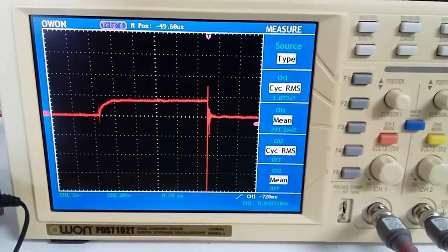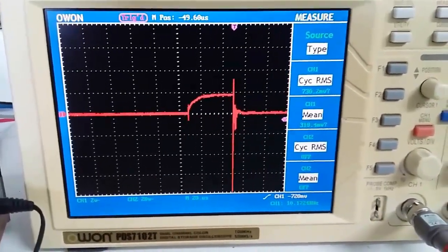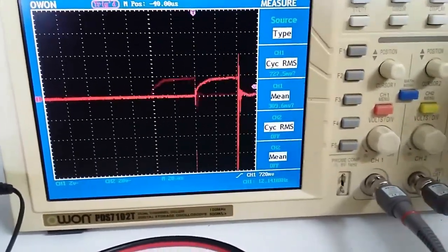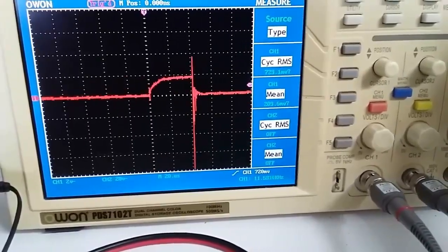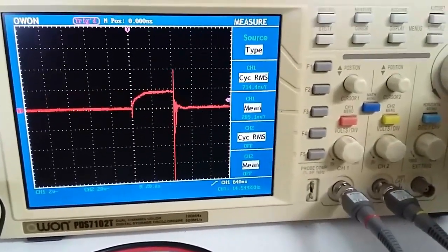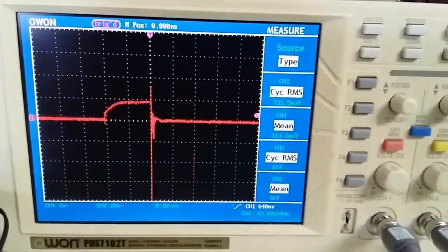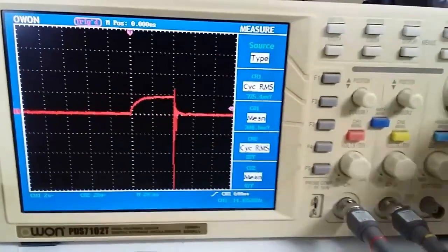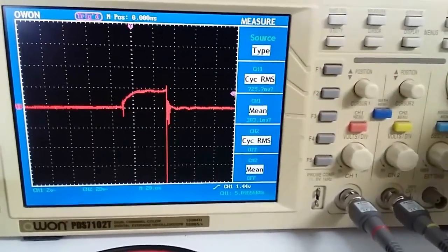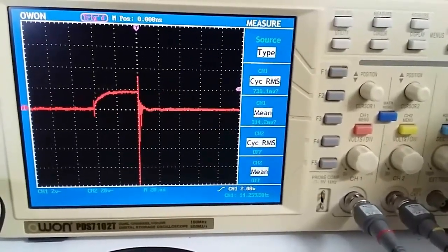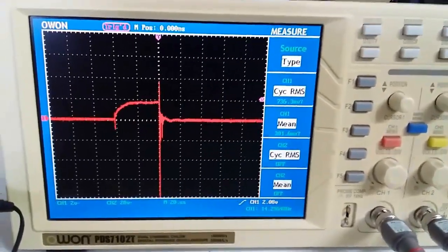frequency it might be. Alright, so we've wound it back a little bit. Let's see if we can get it triggering on the start so we can see it. There we go. Okay. So that is wound back a little bit, and that is actually, believe it or not, 10%. So we're looking at 10% duty cycle for 2.4 kilohertz. Okay,